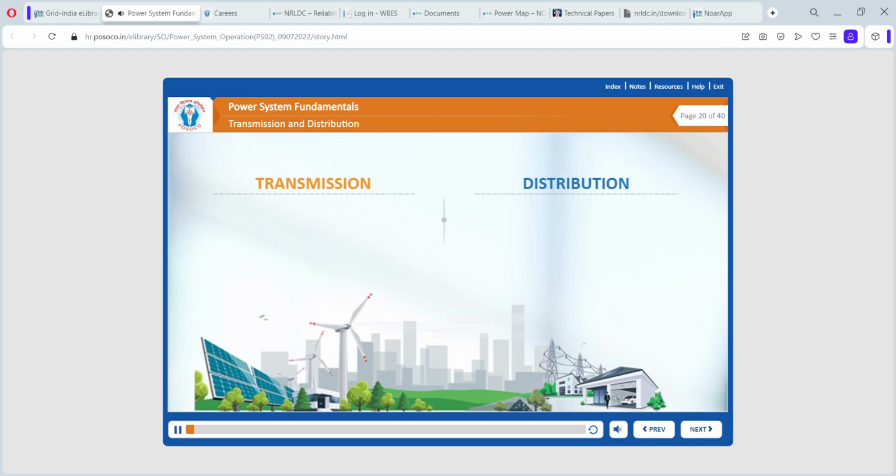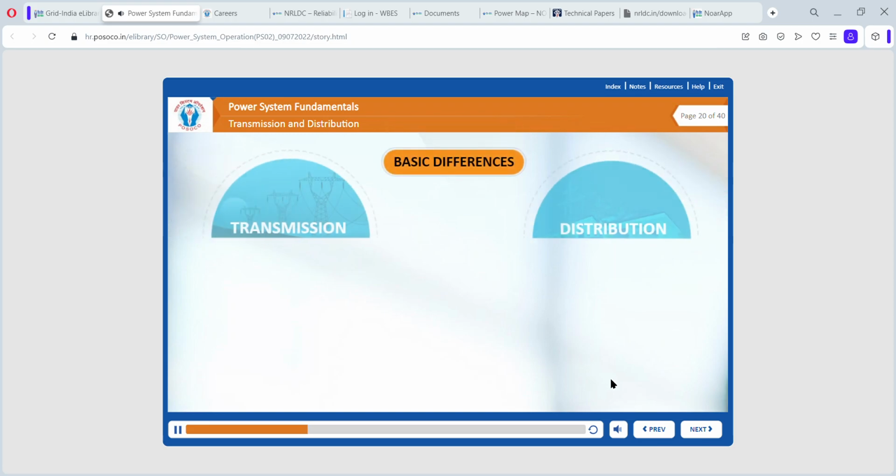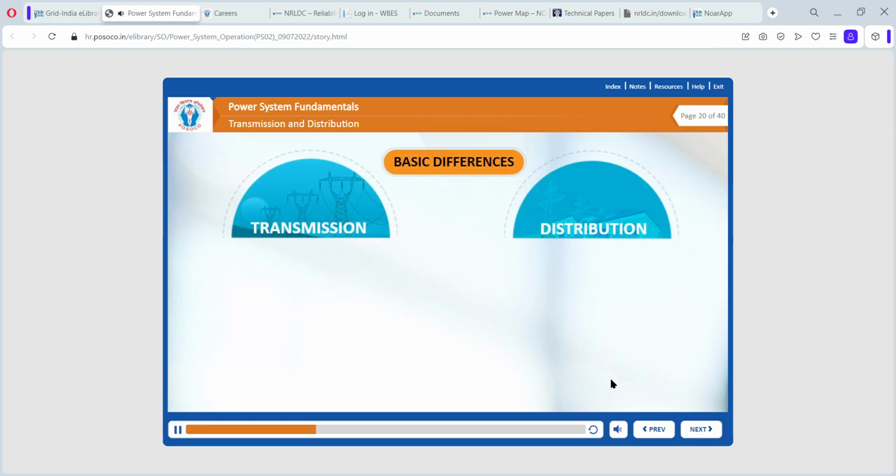Transmission and distribution are the methods to transfer electricity. The transmission power lines are for long-distance, high-voltage electricity transportation, whereas distribution power lines are for shorter distances and lower-voltage electricity transportation. To illustrate, transmission lines are the power lines you might see on the side of the freeway, while distribution lines can be seen on the sides of streets. Furthermore, we shall look at the differences between the two.